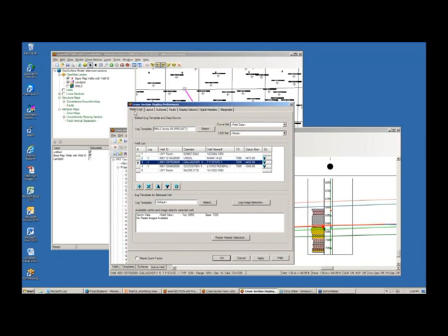I like to work from left to right, and here the Wells Logs tab acts like the active well tab. You can select a well, you can see what available data there is for that specific well, you can change the template of that well, and you can associate it to maybe other more sophisticated curves in Prism or UDEs that you have created.